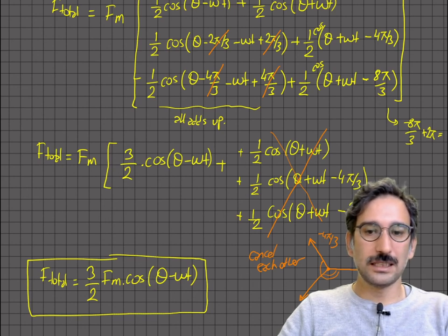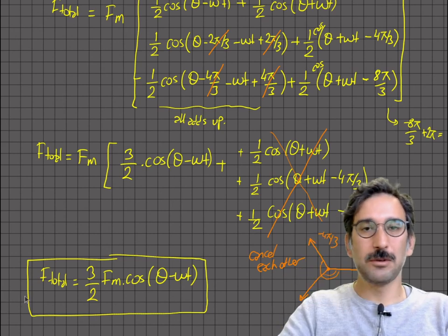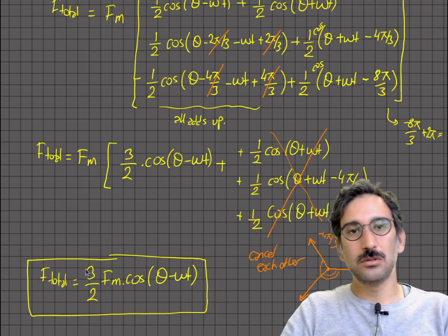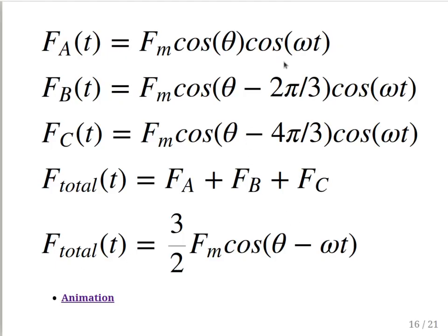Okay, so that is the same term making the MMF rotating, and its magnitude is not 1 but 3 over 2. Again, you see here, sorry about that, I will fix that in the presentation file. But once you add those things, you have that waveform.